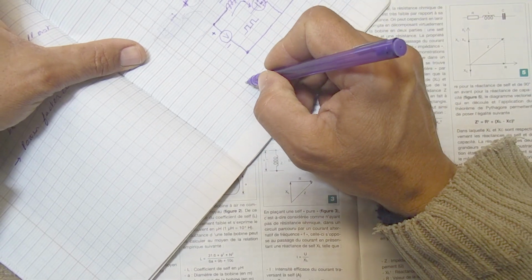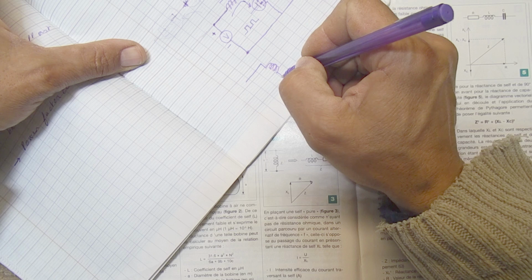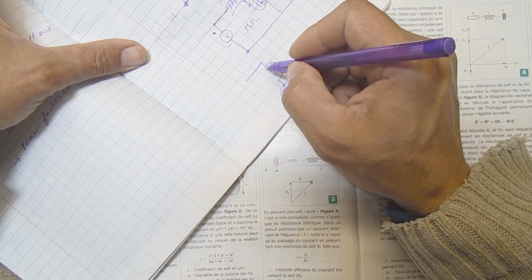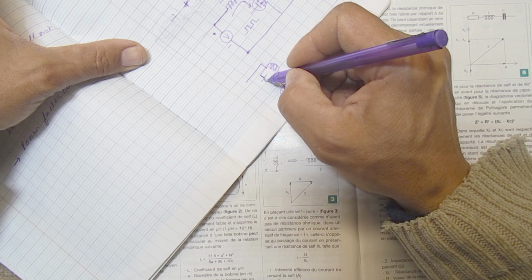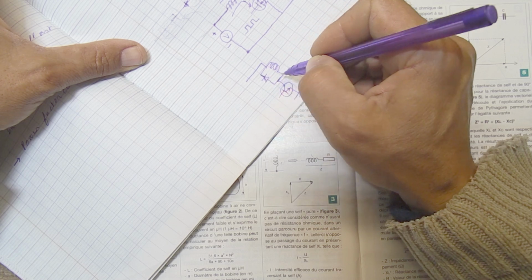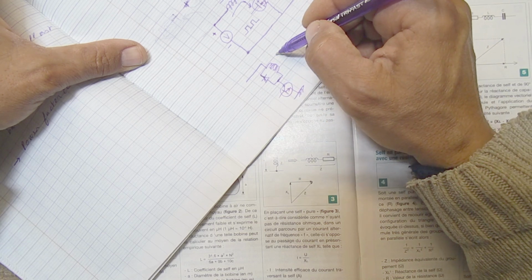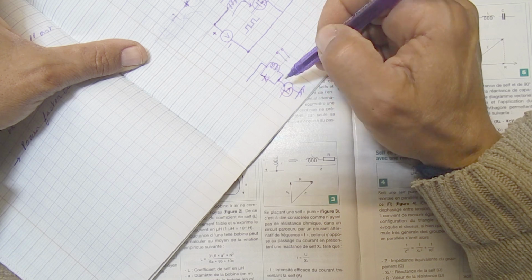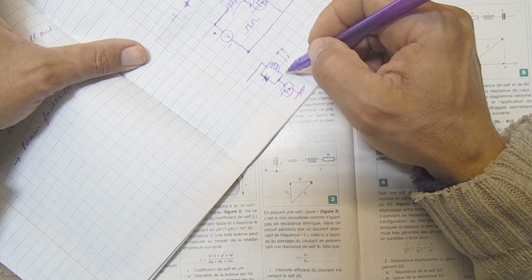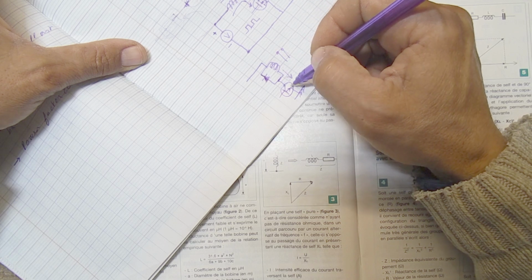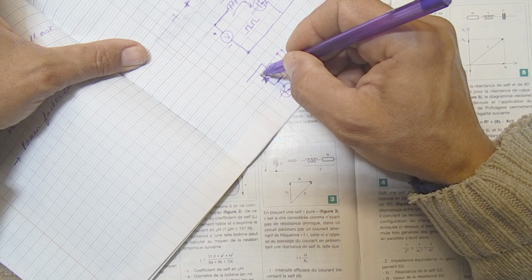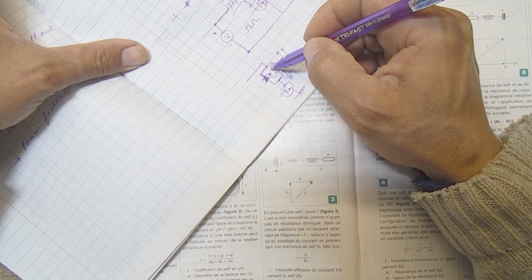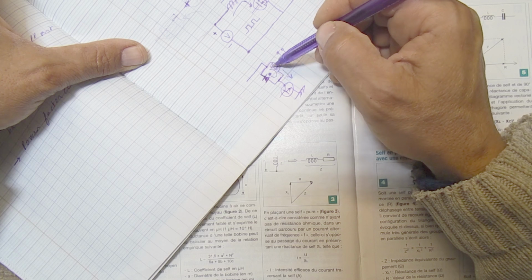For example, in the relay, if we have here the coil of the relay, and here we have a BJT transistor, we use a diode to protect the transistor. Because when we energize the coil, here we have the contact of the relay, it will store energy, and when we turn off the transistor, this energy will flow here and damage the transistor. So we put this diode here to short the coil, so the current will flow in this loop.